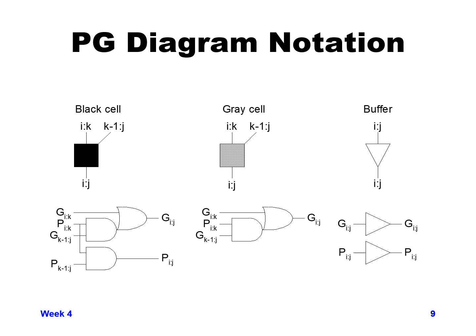A more hashed cell, in gray or other colors, if it's not full black, has the generate and propagate coming in and just generate going out. And if we show a buffer, that means we're just buffering either the generate value or the propagate value; whatever's coming in is what's going out on a given bit. So just keep that notation in mind for the upcoming foils.